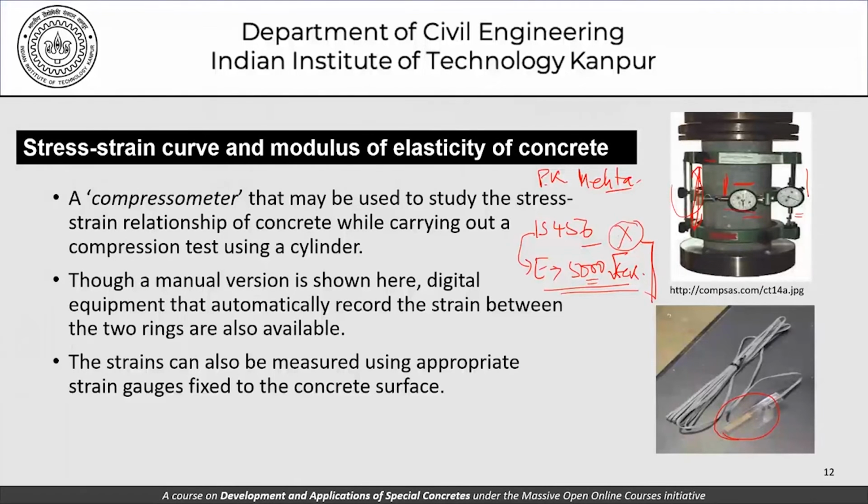I may also add that in the modern day and age, most of the testing devices, the UTMs, have provisions to be able to record the stresses and strains. Not the stresses and strains exactly, but the loads and displacements. And you can convert that to strains and stresses using initial values of the dimensions of the cube. And that's a fairly simple exercise to do.